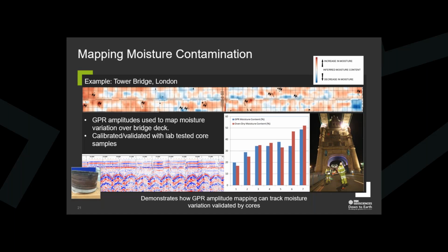The client had concerns about the longevity of the plywood material and was specifically worried about moisture getting in and deteriorating the wood. We carried out some experimentation in our workshops after the inquiry, and we were able to develop a technique and a methodology to detect and measure the moisture within the plywood, which essentially involved measuring the apparent thickness of the wood as it appeared in the GPR data.